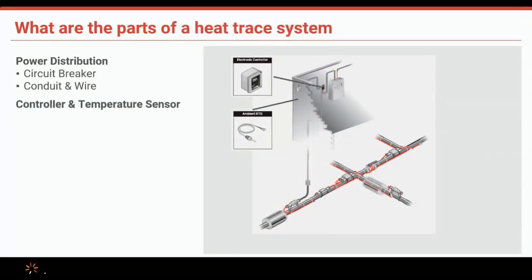In between the power source and the heat trace is a controller. Again, that could be an electronic controller with an RTD sensor. It could be a thermostat. Do you need to have a controller? I get this question quite often. With self-regulating cable, the black and white answer is no, you do not.